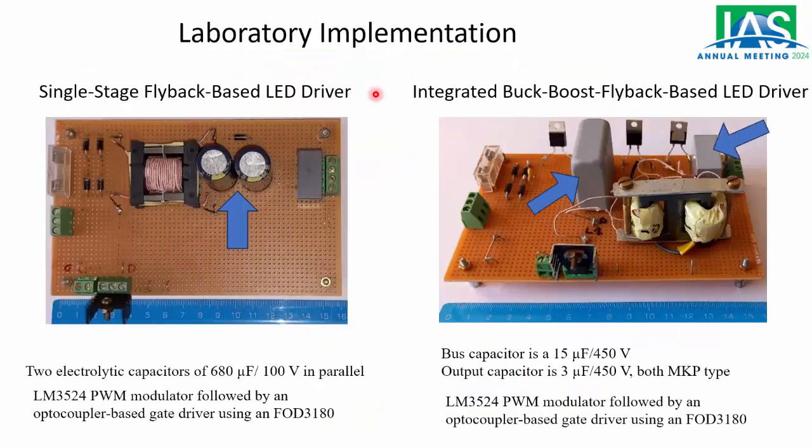And these are the laboratory implementations. And this is the single stage flyback based LED driver. So this is the inductor. We have used two electrolytic capacitors here in parallel to implement the output capacitor. This is another film capacitor, a small capacitor to do filtering at high frequency. The rectifier, this is the switch. We are not showing here the control circuit.